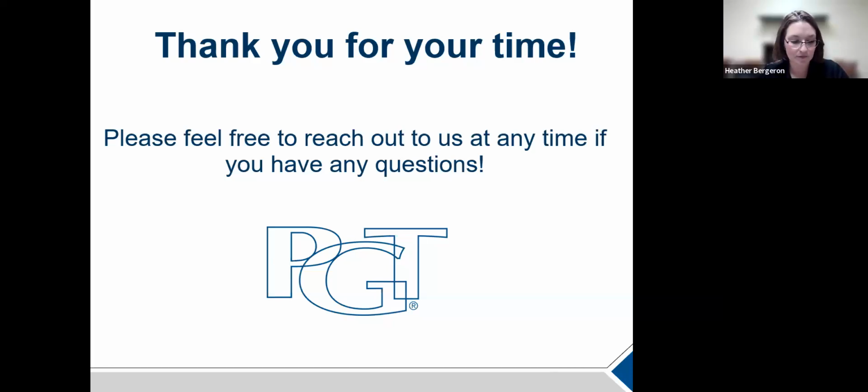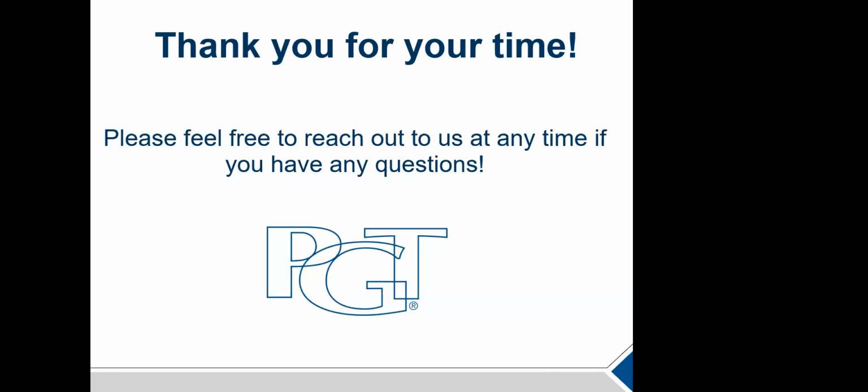Thank you. Okay, the answer is that they're basically related, but it doesn't necessarily mean that. The visible transmittance is going to be how much light actually is allowed to come through the glass. Solar heat gain coefficient can be controlled with the low E. So you can still have a low E and still allow light to come through. The low E is basically going to deflect a certain percentage of the amount of ultraviolet rays of the sun and sort of bounce them back. I mean, it's extremely effective.